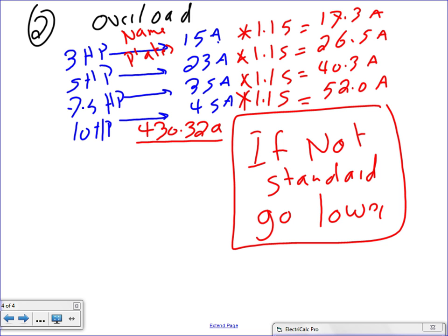What does the overload do? A half banana engineer like Chad bought a pump that's supposed to pump for a 4-story building and installed it on an 8-story building. I overloaded that pump. A conveyor that's supposed to move 50 pounds, you put 100 pounds in it. It will work over, and the overload trips over time, guys. It might sit for half an hour, and then trips.